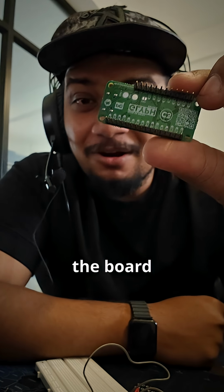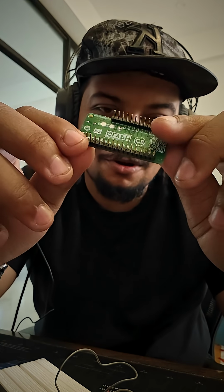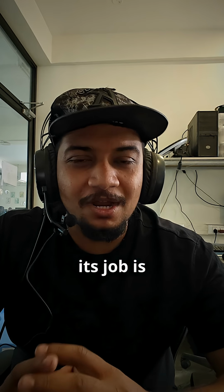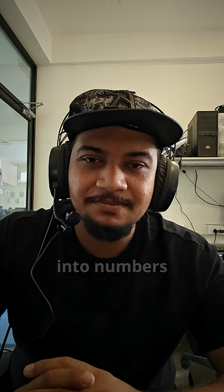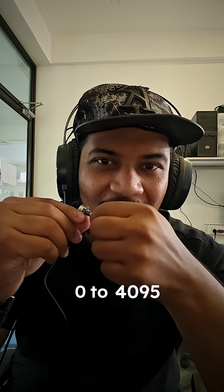But the board cannot understand voltage, it can only understand numbers, right? Well, inside the board there is something called ADC, analog to digital converter. Its job is to convert voltage into numbers. So instead of just on or off, we get values from 0 to 4095.